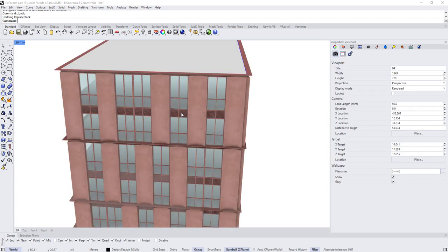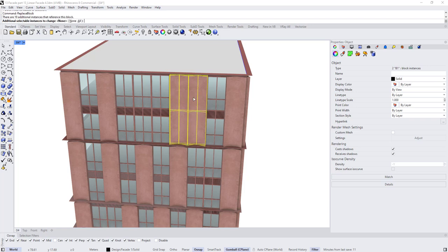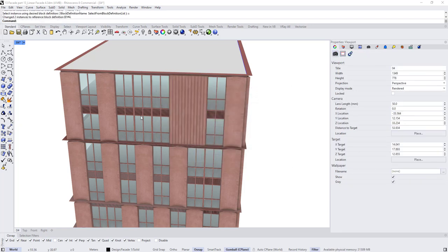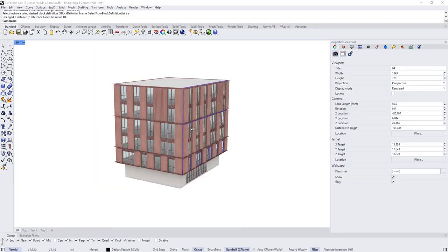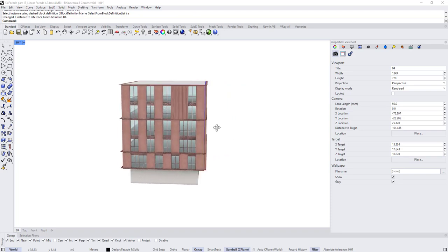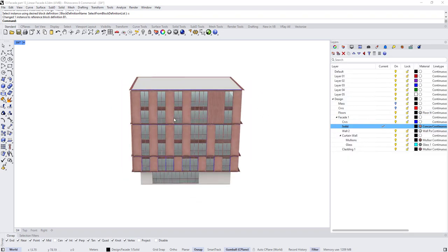You know what? Press Ctrl Z. Scale here. Scale by -1. Select this one and this one. Replace. Right click, S B1 number 4. Replace this one. Enter S B1. Yeah, this looks good. Now the last thing for this one, this facade and this facade, I'm going to just mirror this.